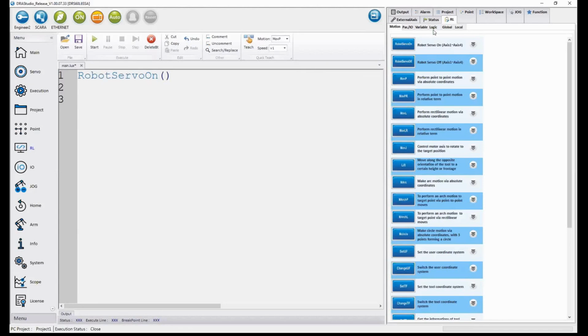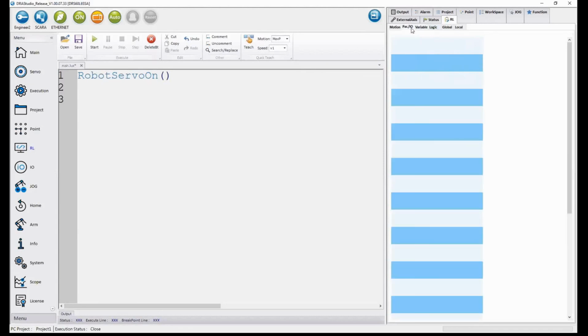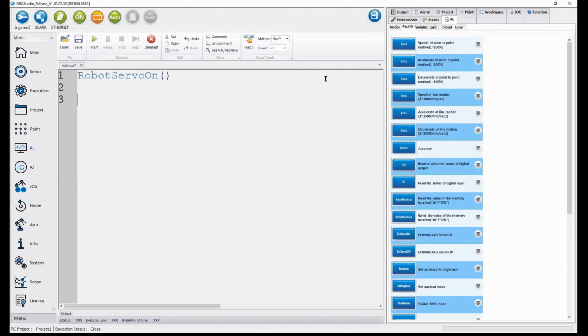Okay, and then now I want to set a speed in the beginning. So you can see here also many buttons you can just click. So now I insert speed joint, acceleration joint, deceleration joint, also speed linear, acceleration linear, and deceleration linear. So we define 2 different groups of speed. For the speed joint, that means for point-to-point motions, and the unit is percentage.